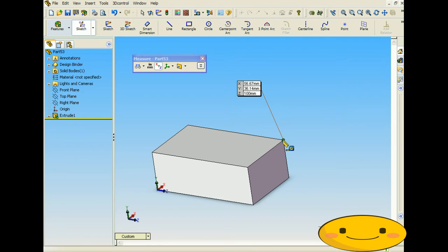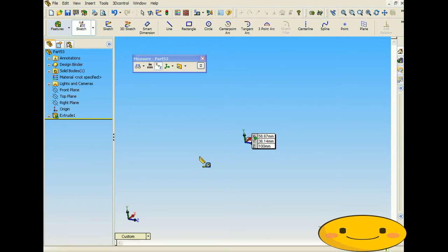So using this tool, you're able to see where you are in the position. So even though the coordinate system's here and the part's here, sometimes when I'm working on a part, this is the part here, but really the coordinate system is down here and it begins. So it's a much larger dimension that you get all over. So this tool also lets you see where, in the whole grand scheme of things, your part really is, if you select just a point. And that concludes our tutorial on how to use the measure tool within SolidWorks.